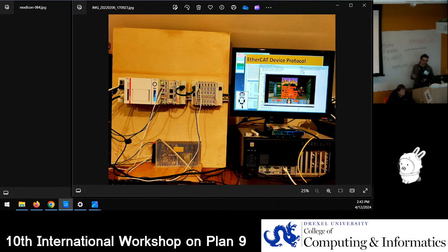And with just a little bit of math, we're able to translate a byte read call through a file and then map it to a function code to get the data out of the PLC and return it as a stream of bytes. And I did that using a very simple little Modbus library I came up with. It only concerns itself with serializing a function code into a frame and sending it out to the server.